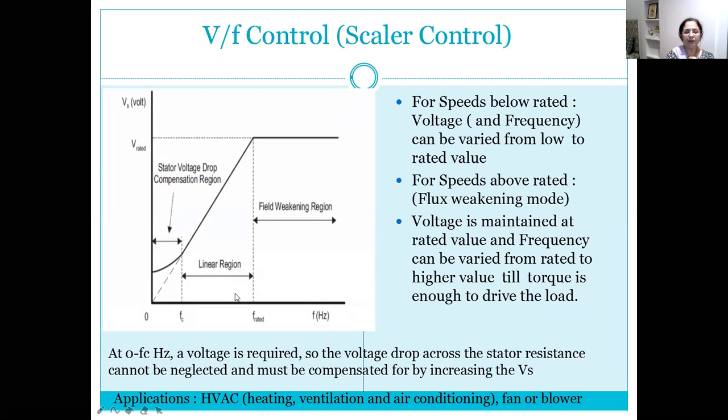Whereas after reaching the rated frequency and rated voltage, at this point, we cannot increase it further above the rated frequency. There are reasons for this. Proportionately we will not be able to increase the voltage above the specification or rated voltage. So we need to maintain the rated voltage constant even when we try to increase the frequency.